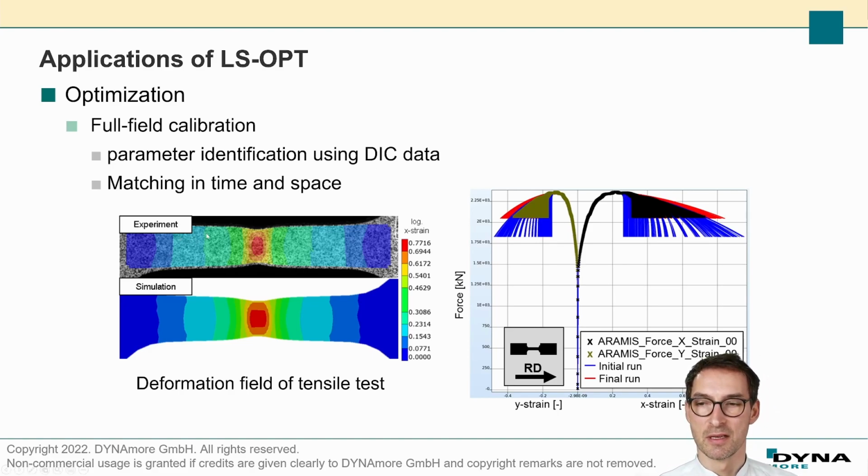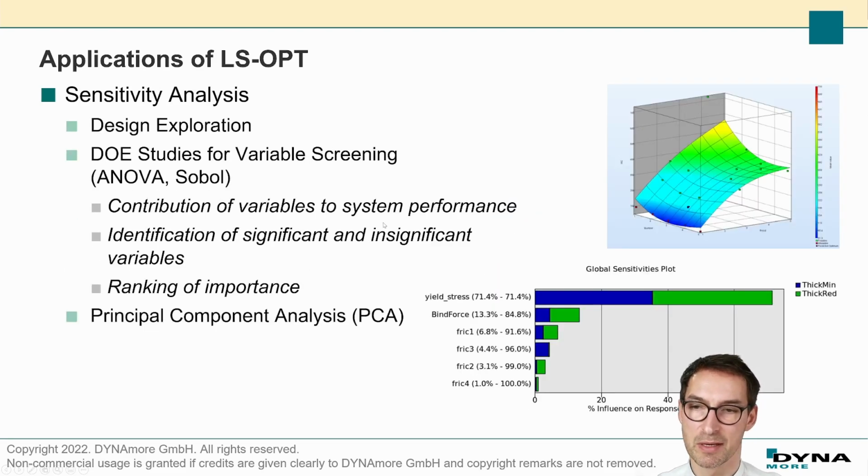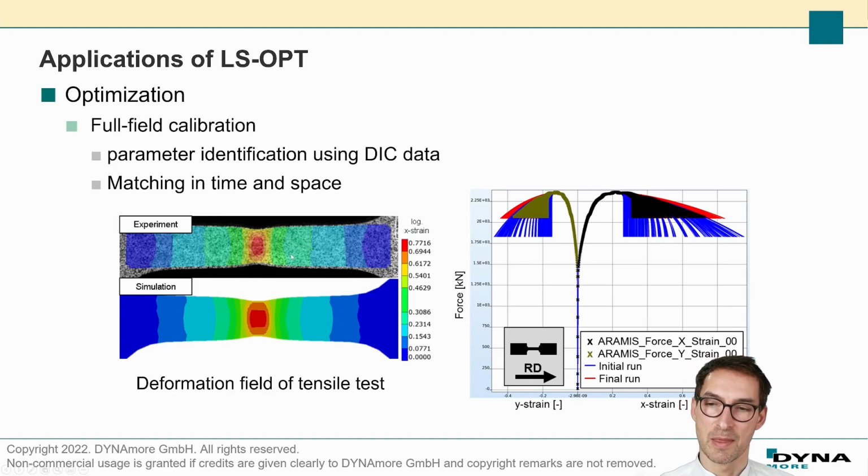So what you do is you create a tensile test, you have this speckle pattern on your tensile specimen, and then through digital image correlation, DIC, you're trying to compute a strain field based on the movement of this speckle pattern. And then, of course, it means that you not only have force and displacement, you also have a whole strain field.